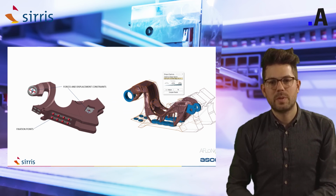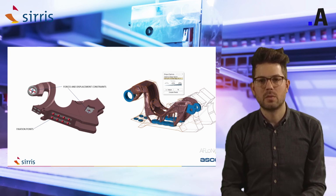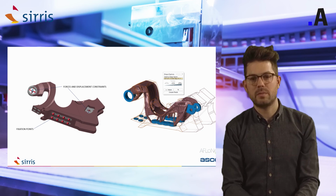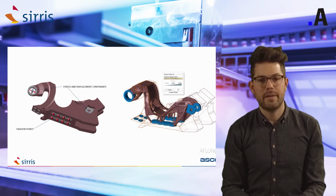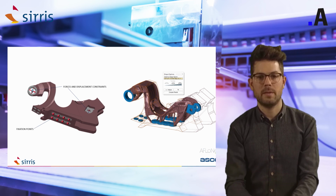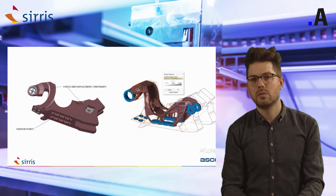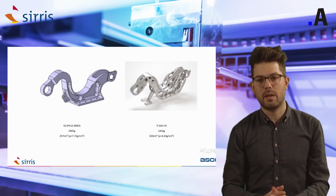An example of this topology optimization process is this part. It's actually a gooseneck bracket project we did together with ASCO. On the left, you can see the design space we had in red, the non-design space we had in gray, and actually we applied all the fixations, all the load conditions onto this design envelope. Then we started a calculation, and on the right you can see the solution which was calculated by the computer and which we used to come up with a new design.